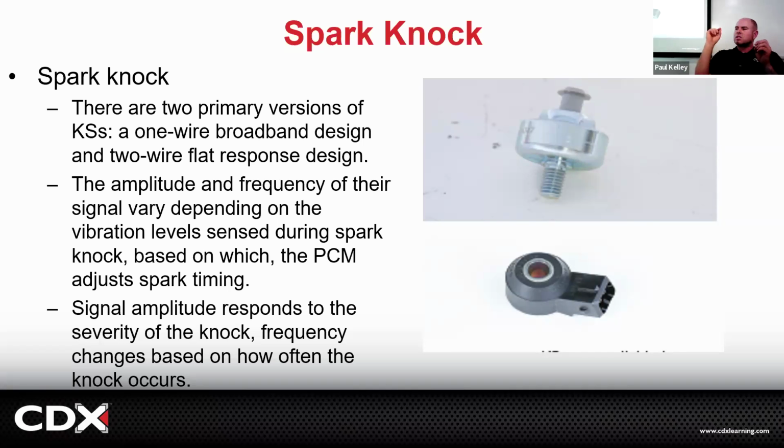So hold that thought. Some systems can measure the ionization and that it occurred before the spark and therefore know, hey, this is out of control. But most of them will use a knock sensor. If you have a flame front over here and then the spark occurs and you have a flame front colliding, that's going to be pre-ignition and detonation. It'll hear that in this microphone and it'll be like, oh, retard the timing. Don't give me 30 degrees before top dead center. Only give me 10. You lost a bunch of power, but it saved the engine. Yeah, that's good. Go ahead, Refugio.